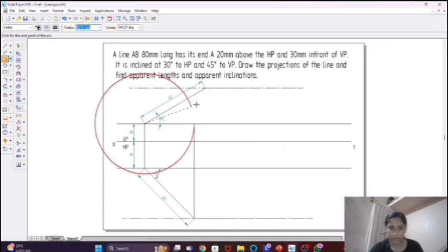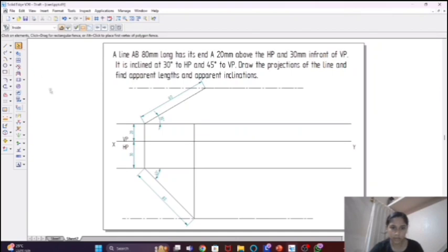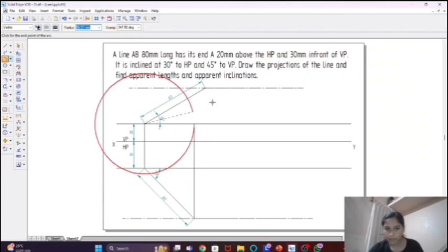So it's not showing me correctly, so let me construct this first. Use arc by center first on the reference line, then on the 90-degree line. So you can draw like this only. Afterwards you can trim using the trim option. So let me make it a continuous circle.